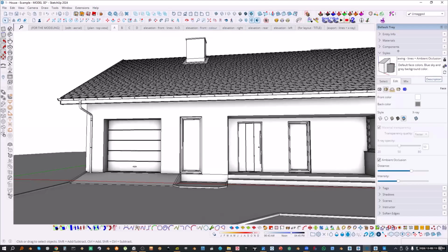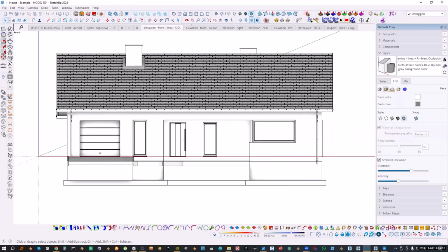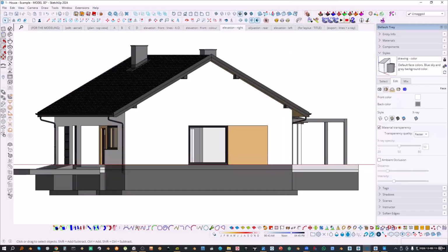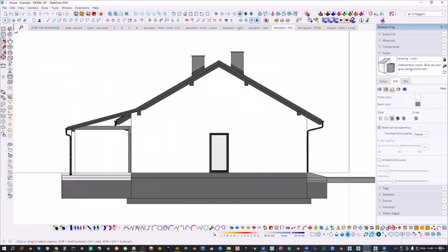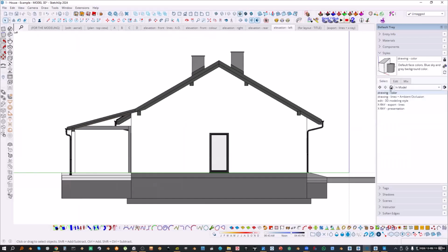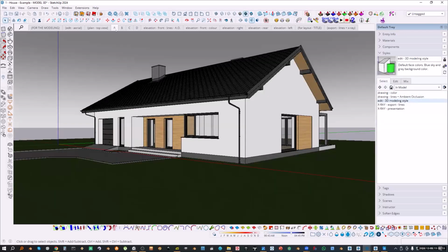I did it earlier with the scenes. One with the color, then the side. And you don't really need to set each elevation or each scene with all the styles in SketchUp. You only need one to make sure that the style will be saved inside of the SketchUp file. So once we have this, and we also have some perspectives, we can then proceed into layout.